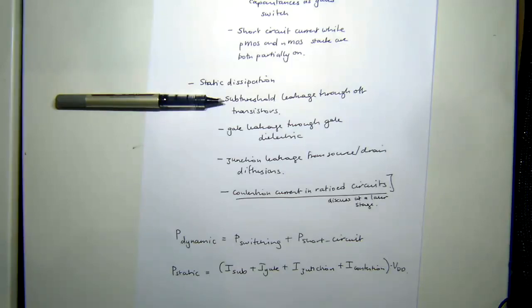So what happens in this, okay, so usually you've got, and this is VG, okay, and then you've got, well, almost something like this, right? So if VGS is less than VT, you still get current going through the transistor, right? But it's small. It's not as large as when it's on, right? And this is what we're talking about. We're talking about there's leakage current, or sub-threshold, right? So this is the threshold. We're below the threshold, but technically the current isn't zero, right?